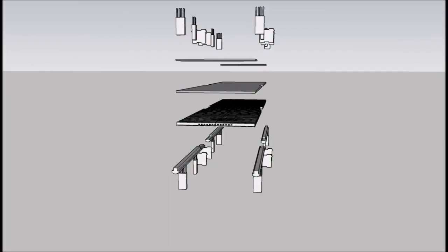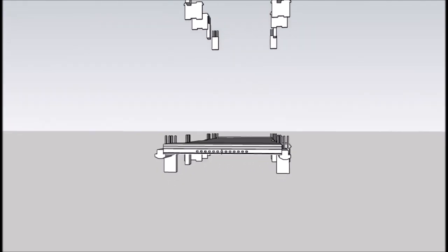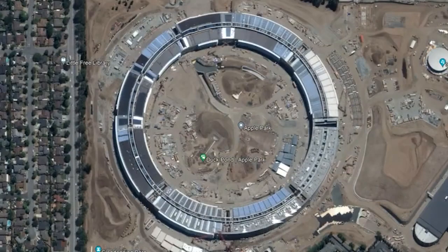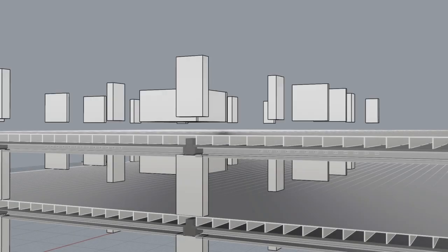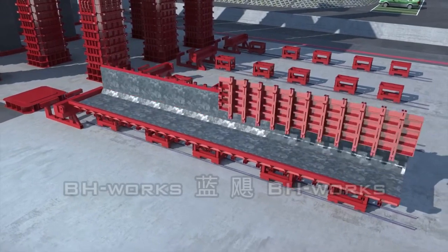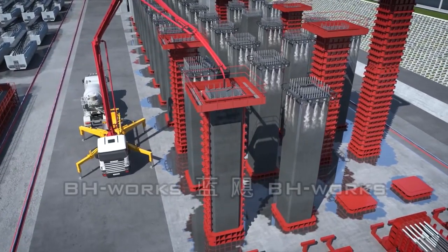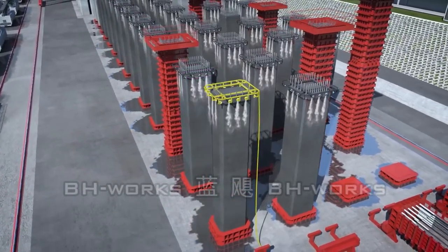This is our 3D modeling, which simulates part of the construction of Abbey Park. Now, we're going to introduce the main structural members in Abbey Park. First, the column. For columns, molds are made and prefabricated rubber and embedments are installed. Next, the concrete is poured, steam cured, and the mold is demolded once curing is complete.